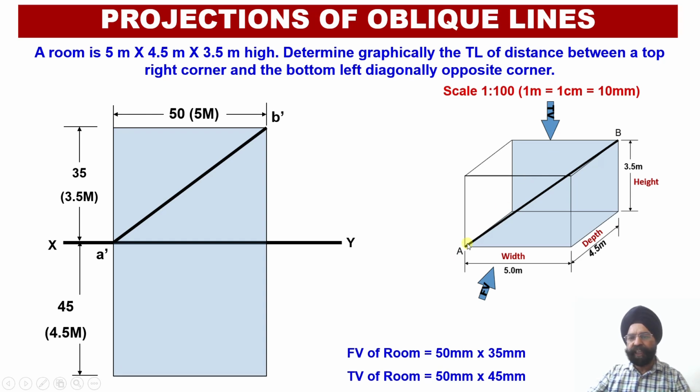Now as we look at this particular string, here we are going to get point A. So point A will be projected at this particular corner over here in the top view. That is, this point will be representing the top view corresponding to the point A, small a over here in the top view. Similarly, the top view corresponding to this point B will be located over here.